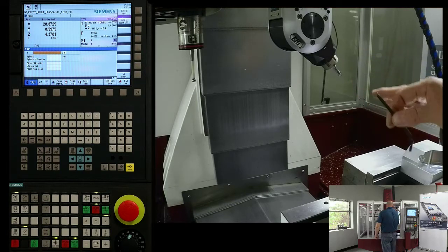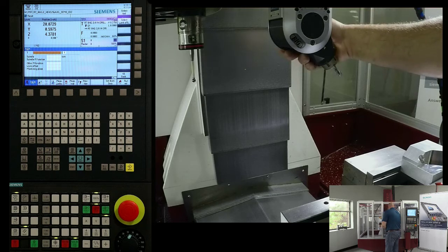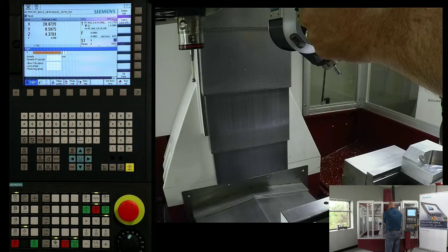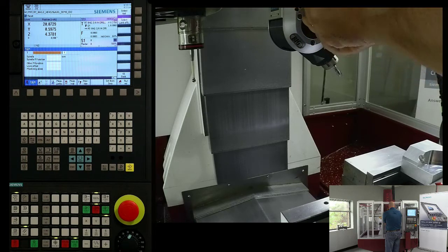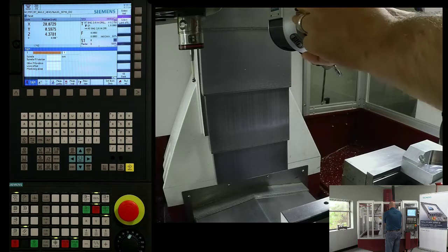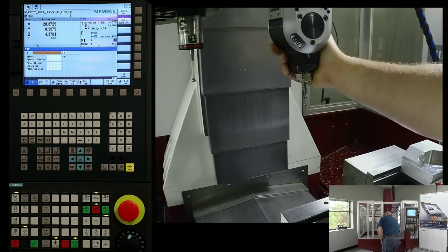We're going to explore that in part 3 and show you how I can set all that functionality up. But for this case, we're going to loosen up our 6 bolts. Then I'm going to back out this set screw, because I no longer want it locked in at a 5-degree increment sitting at the 45-degree angle. I want to set it at 0 first. So I'm going to bring it down.